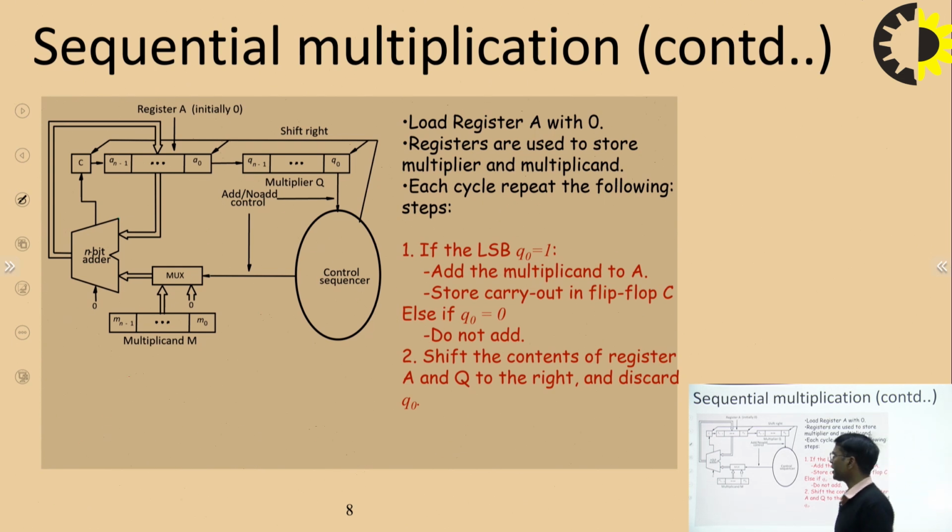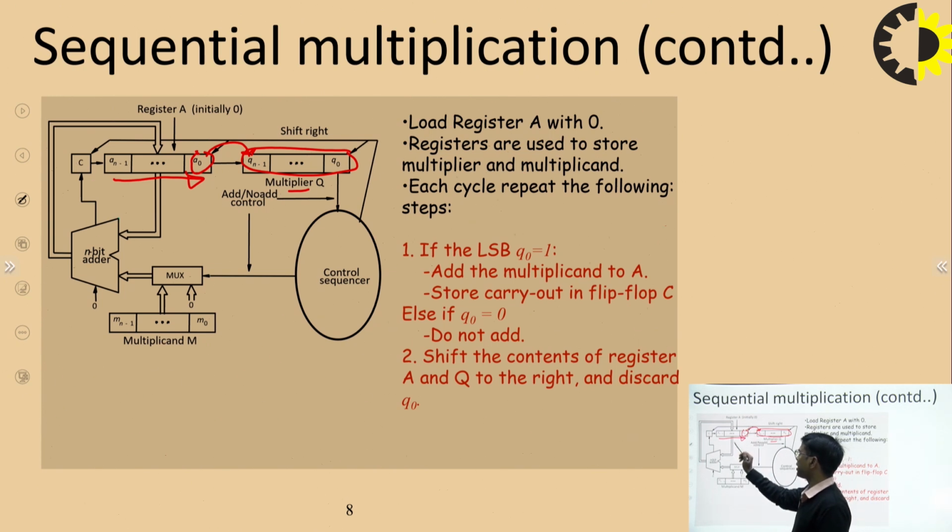registers. Here you can see we have an n bit accumulator register, okay. It is kept at 0 initially, and it has the capacity to shift right, fine. So, the content of A0 can move to the q n minus 1 bit of the multiplier q, fine, and this multiplier q register holds the initial multiplier value, fine. Now, initially the register is kept at 0.